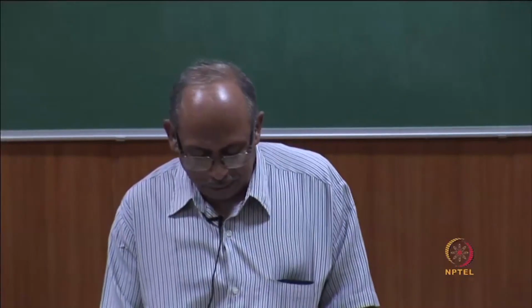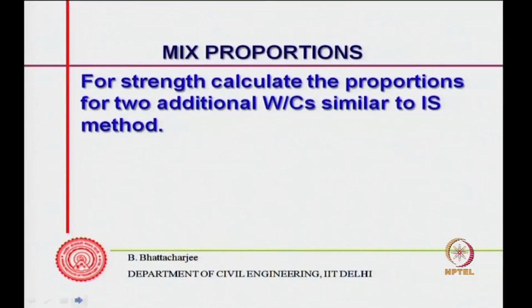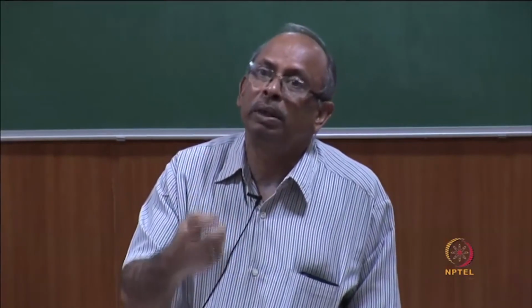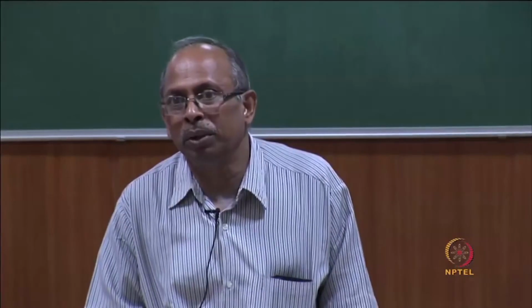So, a similar kind of test can be done to determine the particular superplasticizer. Then add this superplasticizer to get the slump you need. If you still need higher slump, then you have to increase the paste content, which means that you will increase water, cement, and correspondingly the superplasticizer dosage also.